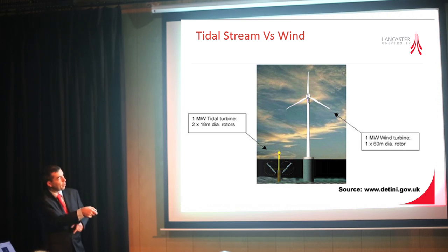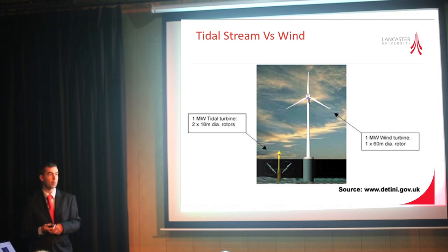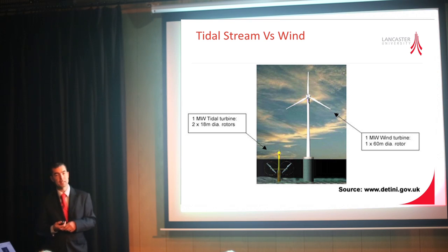Also important to realise that 1 megawatt is now quite old. Typically the offshore systems are now looking up to 5 or 6 megawatts in terms of the size of machine, so they have a rotor diameter in excess of 120 metres. So I would expect tidal devices to go similarly up to perhaps a 30 metre diameter sometime in the near future.